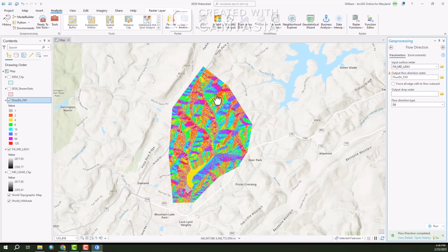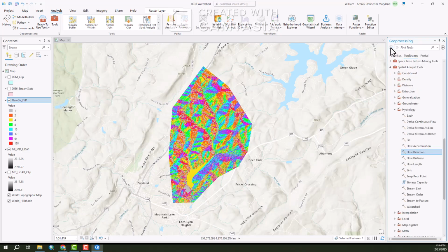We now need to take these cells, and each cell flows into the next one downstream until it finally gets to the last one. And as you get closer to the bottom, they all accumulate together in the river. So now we do flow accumulation. Excuse me. So we back out, hopefully there we go, geoprocessing. We now go to the flow accumulation tool.